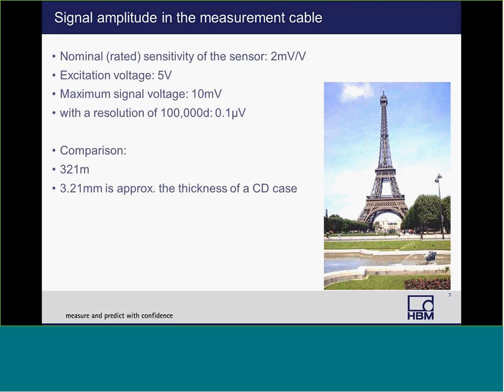So, a little background on our measurement signal. We will hear people talk about a signal-to-noise ratio in measurement, and the basic story is if you have a large measurement signal and a small noise signal, the noise is not going to cause you much problem. But if you have a very small measurement signal and a correspondingly similar sized noise signal, then you can get inaccurate results, or it's difficult to determine what is occurring.